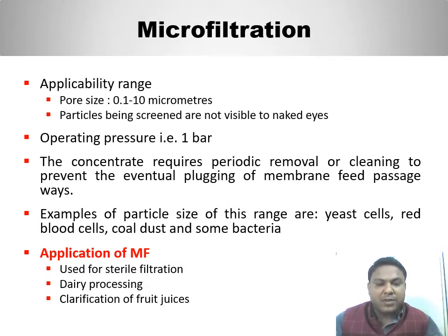Microfiltration, or MF, offers unlimited new process opportunities in the membrane market, especially as a pre-treatment process. Microfiltration provides a low temperature processing alternative to thermal methods like ultrapasteurization for reducing the number of bacteria in fluid milk or in whey as well as fruit juices. Microfiltration is used in the dairy industry for marketing low heat sterile milk. Further, microfiltration membranes can be used to remove bacteria and fat and produce protein isolates and concentrates without affecting the functional properties of proteins due to low applied temperature.